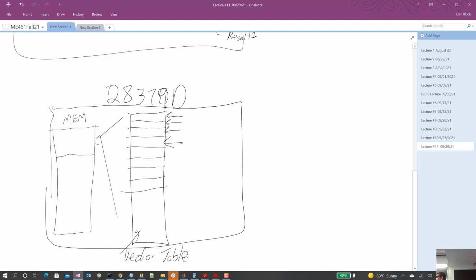And by doing that assignment, saying that vector table element equals ampersand, the name of your function. What does ampersand mean? It means the address of. Ampersand in front of a variable means give me the address of where that's located. So if you put an ampersand in front of a function, it's saying give me the location of where that function is located in RAM.